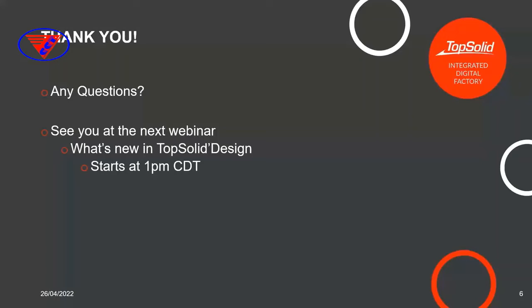But you know that there's tapped holes in there, you know there's reamed holes in there. If you go through free shape, you can identify those back as tapped holes in TopSolid and holes with precision in TopSolid, so that when you go to use method-based machining in TopSolid CAM, you click a button and it's 100% recognized. So it's a way to control things. That's one of the whole ideas there.